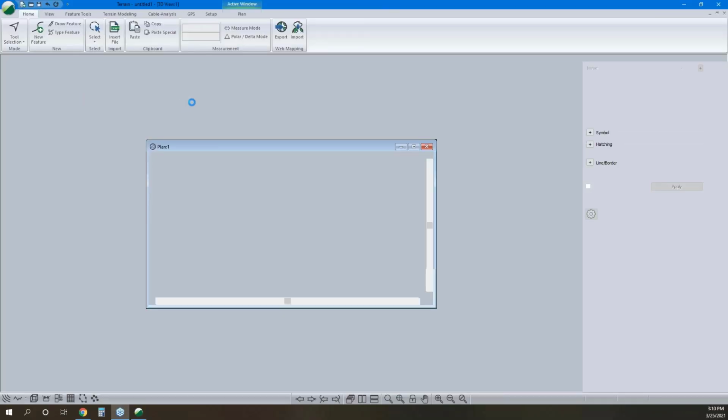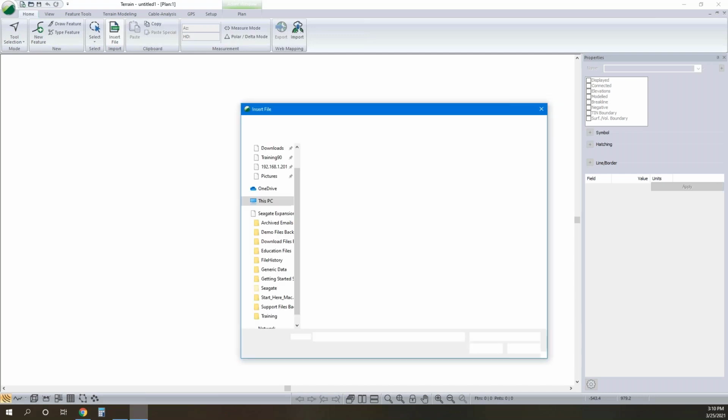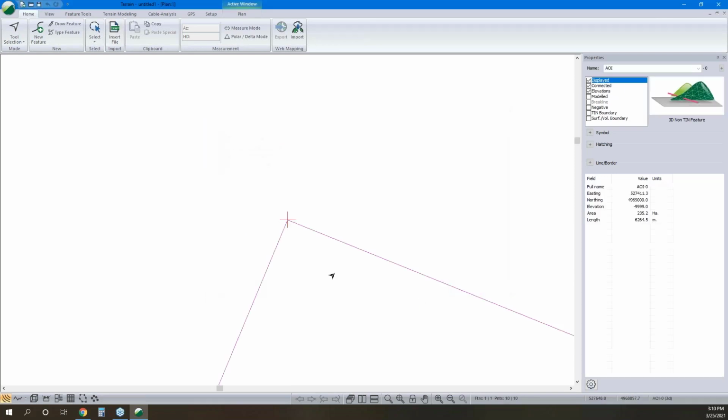And for this example, I was clicking around. I downloaded a bunch of tiles in the area, and I don't need a bunch of tiles in the area. I need about 4. I've also got a shapefile that just shows a rough outline of the area that I'm interested in. So in this case, save bringing in all that LiDAR data, making a massive TIN that can get clunky to work with if it's really, really big, I'm going to thin our data down on import. So I'm going to bring the shapefile in, click open, and there's our area of interest.